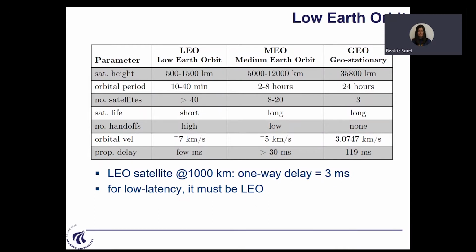It means that the same satellite is not visible all the time for us, but what happens is that we have a satellite pass which lasts a few minutes. So from horizon to horizon, I will see one satellite for a few minutes. This, for the communication networks, means a lot of new challenges. The infrastructure, my base station, which is the satellite, is moving. Actually, it's moving very fast. If I want to keep continuous coverage, I need to have a lot of these satellites all connected to each other.